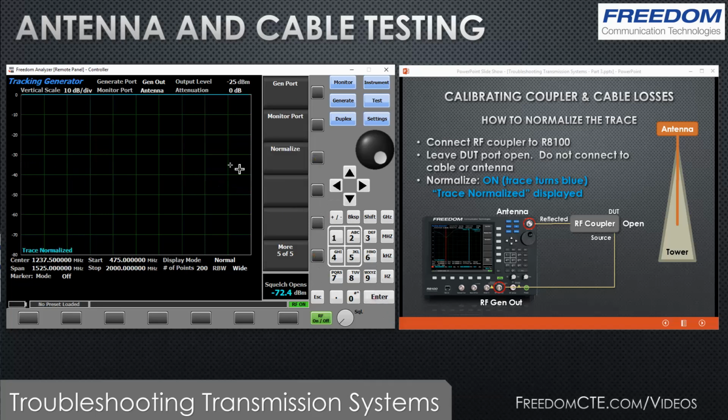Okay, what you'll notice now is that the line has turned from yellow to light blue. It says trace normalized, and now we sit right at 0. So all the losses induced by the system, in the instrument itself, in the coupler or in the cables, have been compensated for.